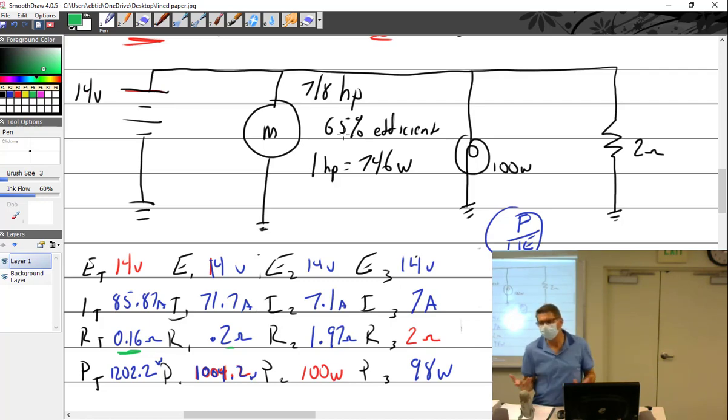All right. So what we would do then is sit down on a piece of paper and say, okay, we got a 14-volt system. I've got this motor, this wattage. I would do this electrical analysis. I would have to put it on a Form 337, which is a major alteration repair form.